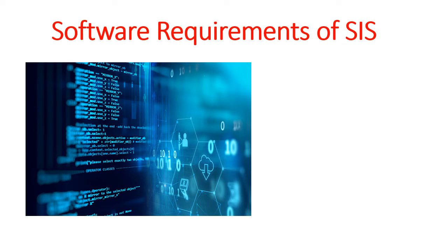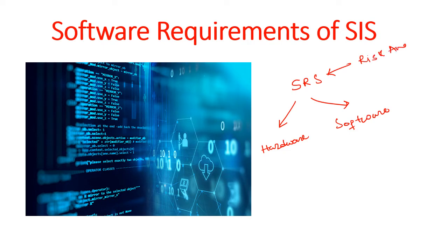So from the SRS, you get two parts. One is the hardware requirement and another is the software requirement. And this SRS actually gets generated out of the risk analysis, which can be in the form of HAZOP, LOPA, FTA, etc.